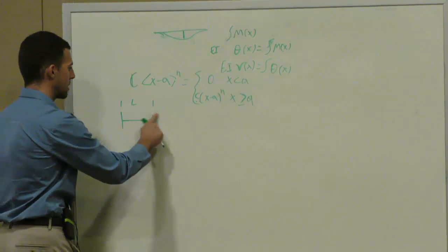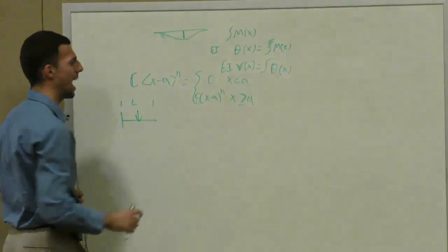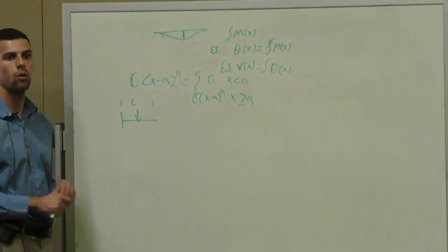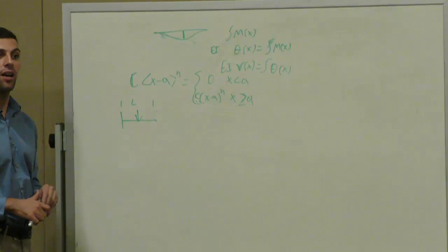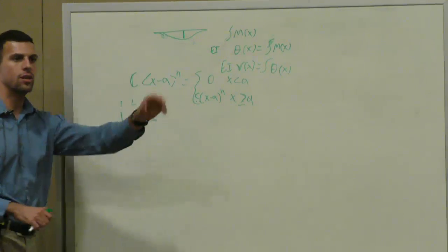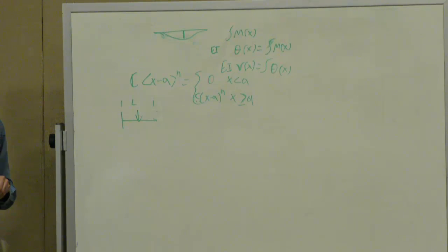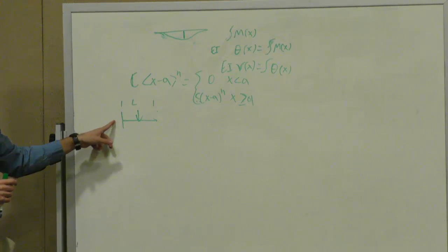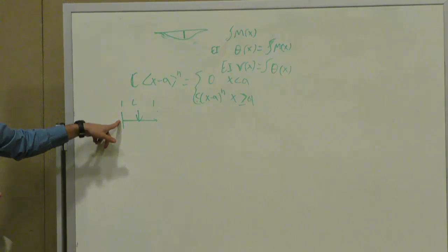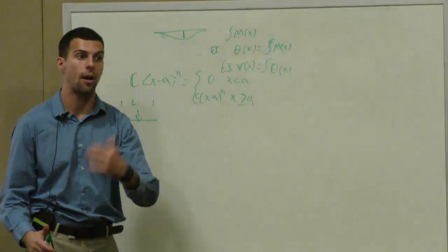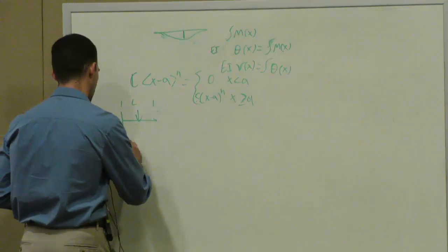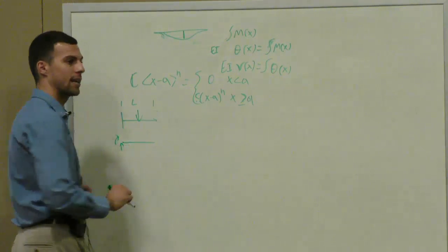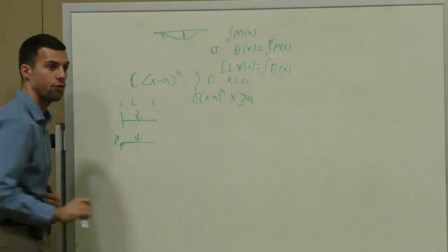In other words, if we had a cantilevered beam like this of length L, where the load happens at 1/2 L, in this case, what's the first thing you need to do when establishing Macaulay functions? You do boundary conditions, but that's not necessarily the first thing. What is the force here called? It's got a special name. Reaction, right? You have to do your free body diagram and your reactions first. So you'll have a moment reaction and a load reaction like that. So there's your free body diagram.